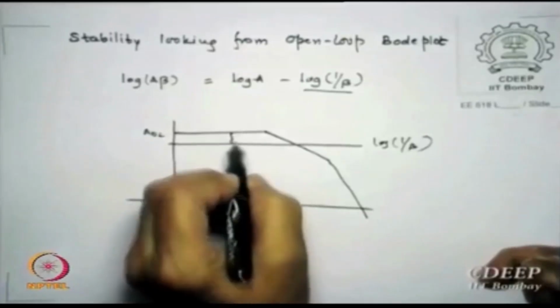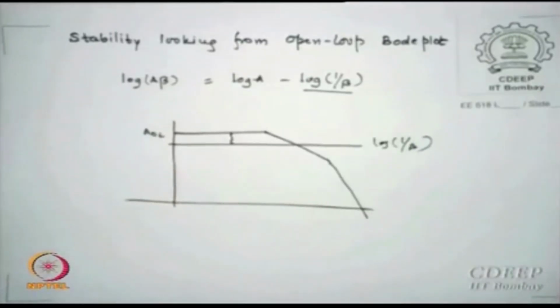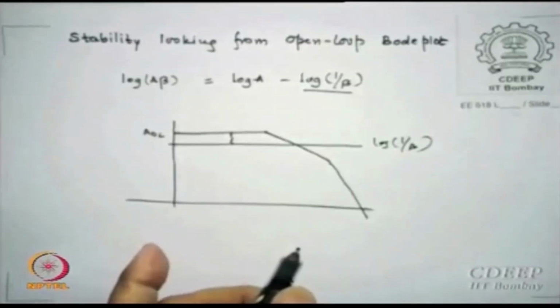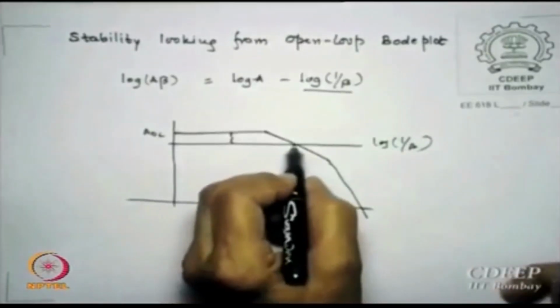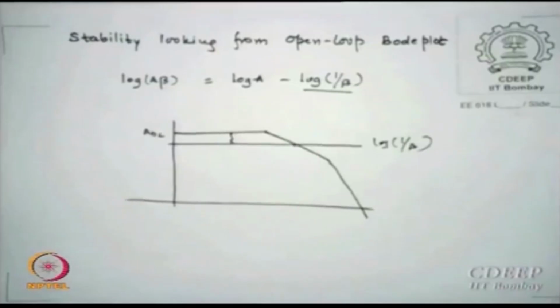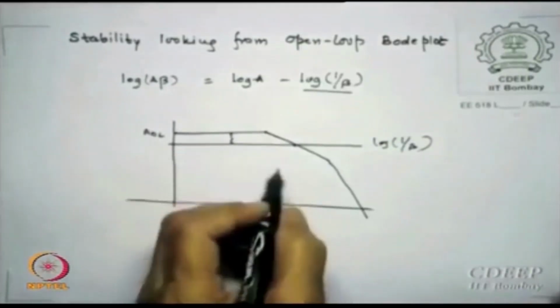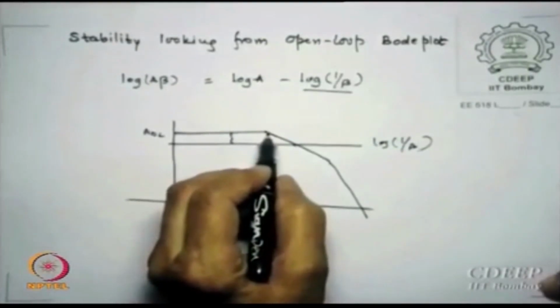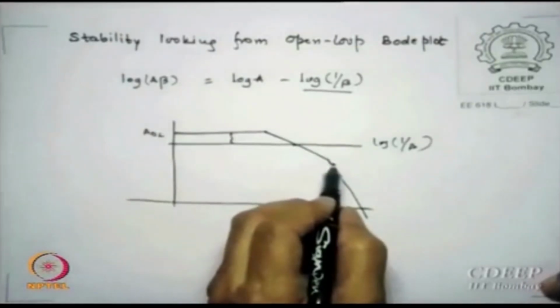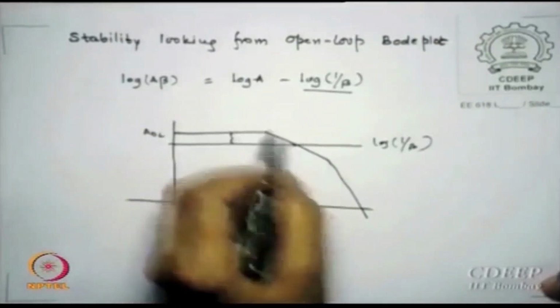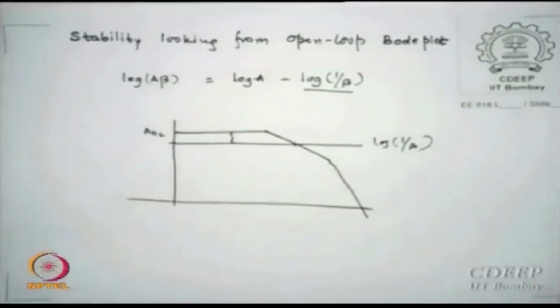So what is this value? This is the loop gain. So what is this value therefore? Loop gain is 0. Is that point clear? This is the point where loop gain is 0. Now if you take the phase for this, it will reach 45 degrees, this will reach 135 degrees, and as long as you are within this range of the feedback 1 by beta point, you can always create more than 45 degrees of phase margin. Is that clear to you?